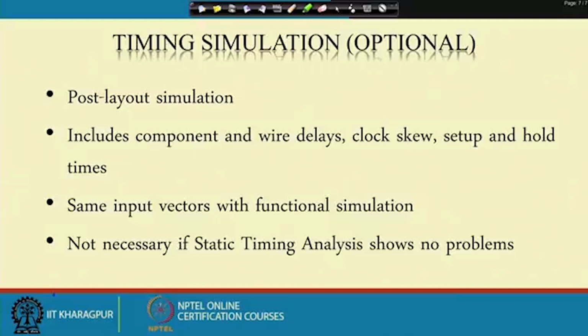Initially I have done the functional simulation. After this synthesis, I have the gate level netlist, and I have to do the timing simulation. In the functional simulation, no gate delay or net delay is included. It only checks whether for 1 plus 1 I am getting 2 or not for a particular adder design.